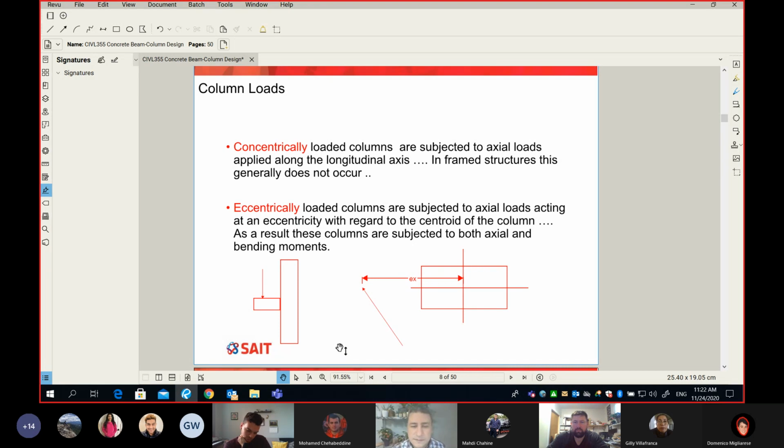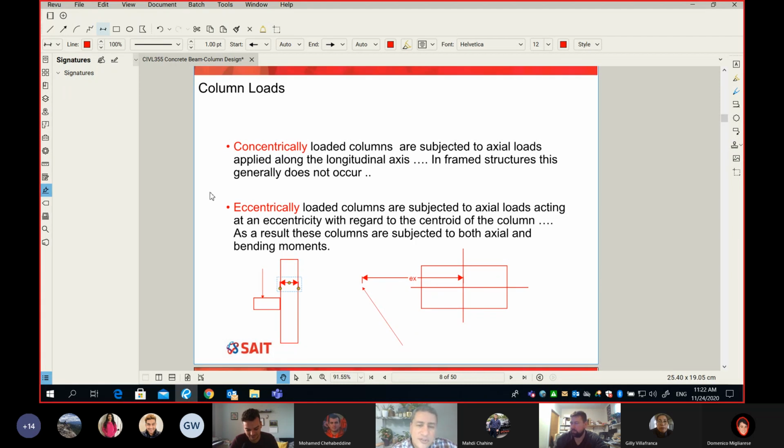What do you think? Well, no, because now it has to support that cantilever, right? Yes. So this is what I'm trying to say here. Remember the cross section is from this point to this point, which is the same cross section here. So even though the force is outside the cross section, it doesn't mean that the force doesn't place a stress on your column.